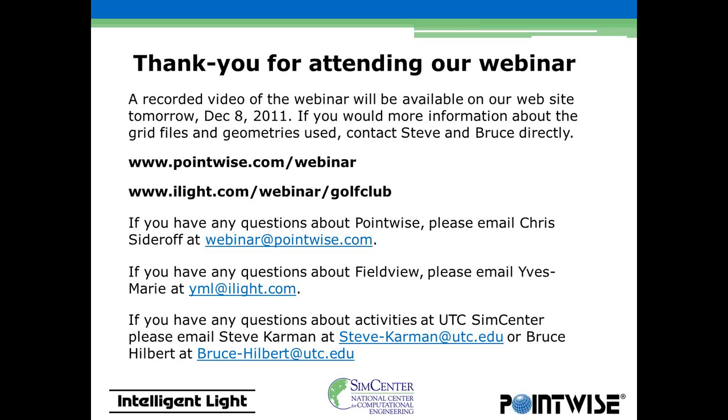So I have a question here for Eve Marie. What are the limitations of the XDB storage? Can it be used for streamlines, for example? Yeah, it can be used for all the post-processing objects that you typically create when working in FieldView. So you could put streamlines in it, isosurfaces, cutting planes. You could also put some particles in it, but for performance reasons, we recommend keeping them separate in a FieldView particle path format. So really I would say no limitation. All of the objects that we handle in FieldView can be saved into those files.